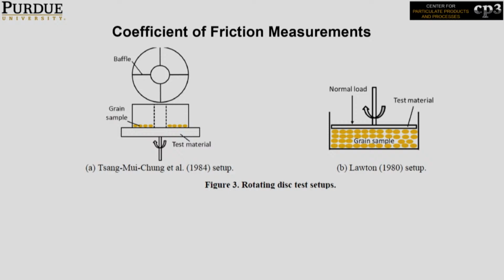And again, very similar to the shear setup. So, it's again a baffle that goes into it, and the grains, when the baffle moves over the grain surface, you measure the friction. Okay. So, there are tons of friction measurement setups that you can develop and use, but there will be some disadvantages. Again, same disadvantage, you will see those movements of materials or rolling of materials that will affect your friction measurement. Okay.